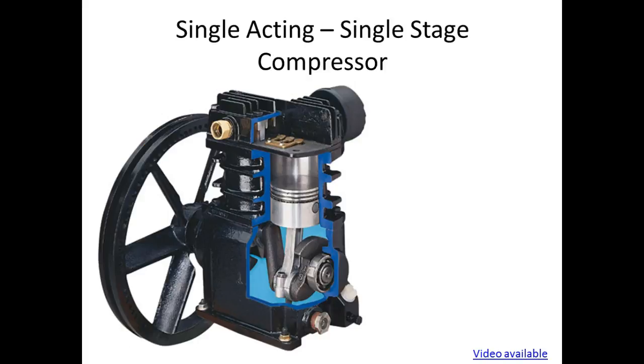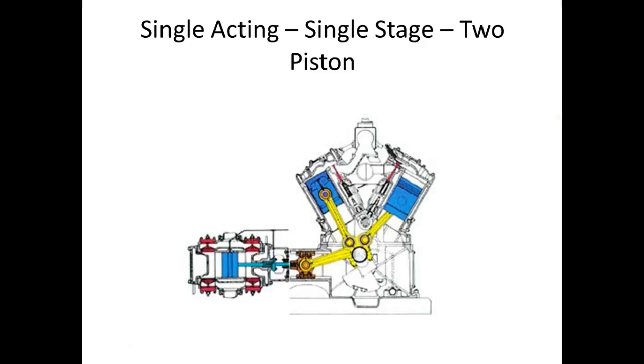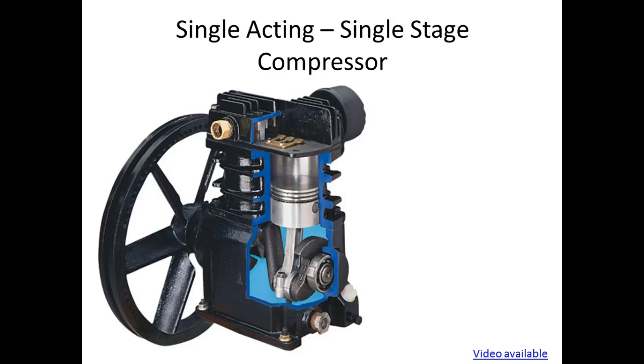Single acting, single stage compressor. This would be where we only have 1 cylinder in there. Most of your residential and commercial compressors use this, 1 cylinder. And then we have single acting, multi-stage. I think there's a video here.